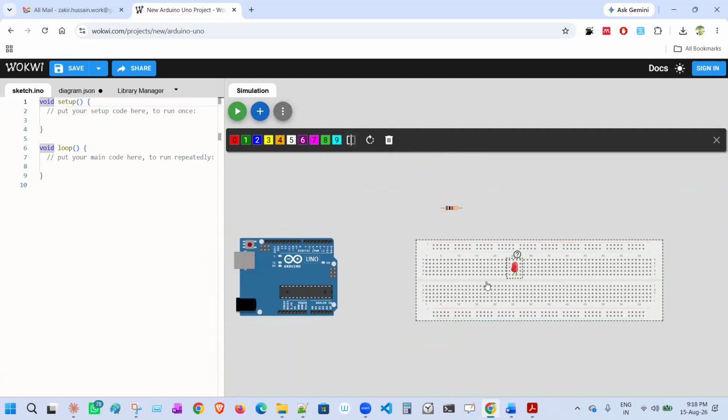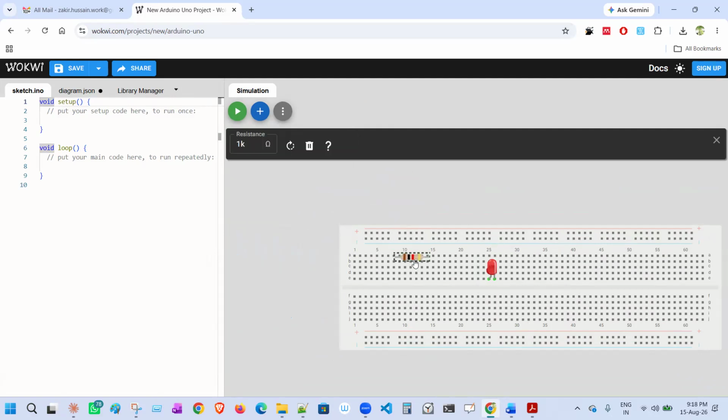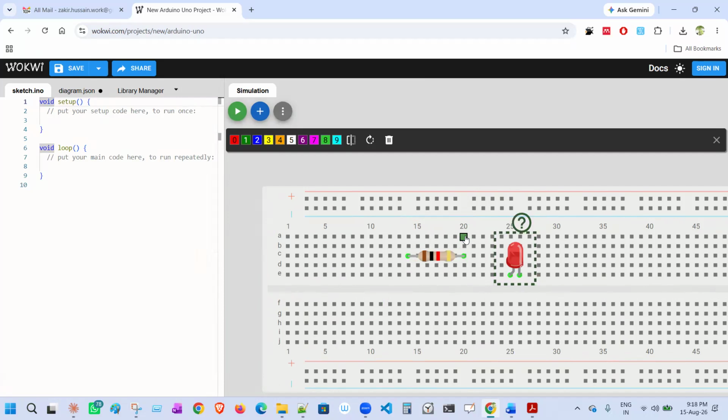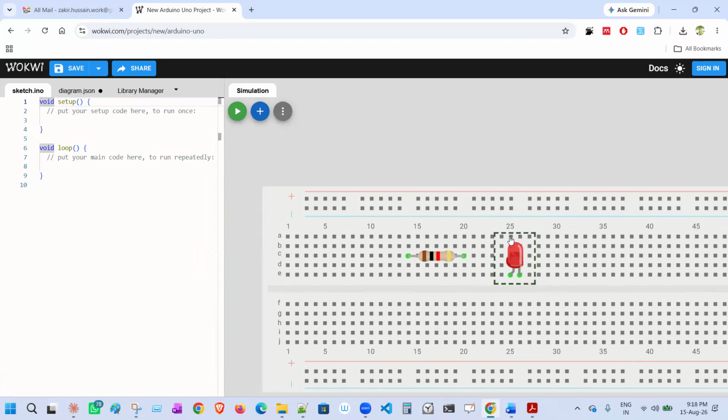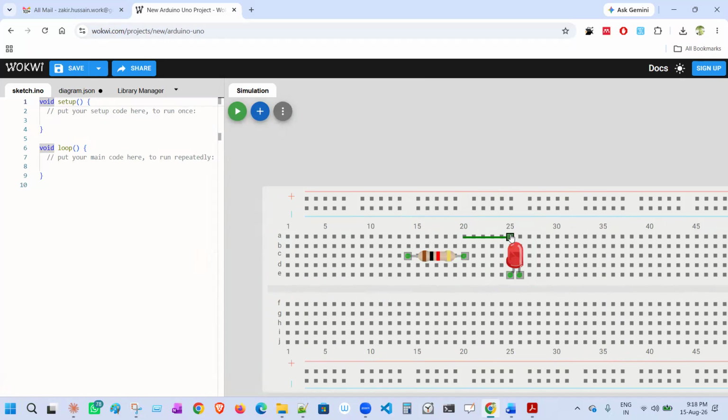Now what you do is you just take the connection from here. Even this requires to be kept. So get this one here and place it here. See how I am placing. I'm just dropping that one where the holes are there. Here, as I said, this column is electrically connected. From this point to this point, I can leave, right? That way, this will get a connection. So let me do that. From here to here. So this point. So now both got connected.